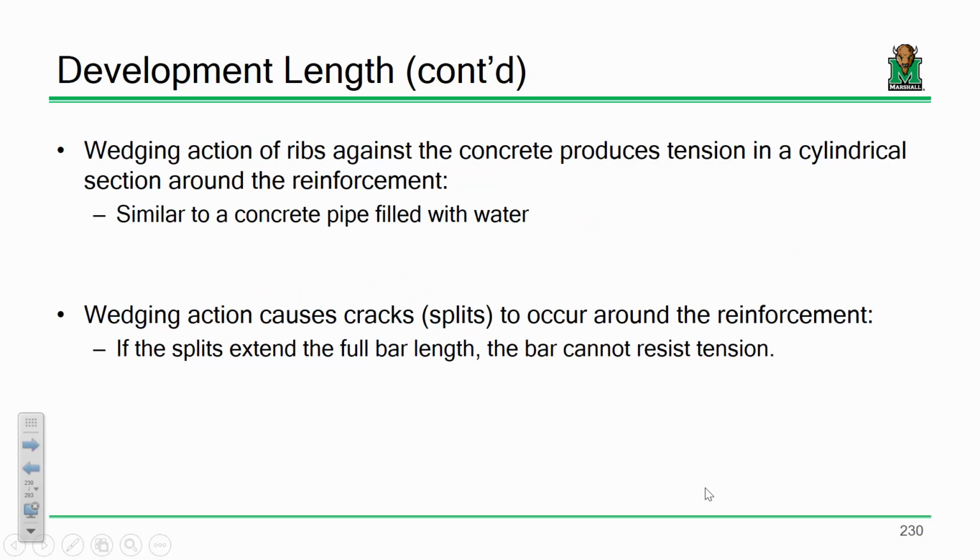Now, I want to show you something real quick. Let's go back to the analogy of the wall and the concrete. What happens with bond failure? Imagine I have that bar embedded into that wall. What happens if I actually start yanking on it? So let's say I have a bar right here. This is a bar of steel, or a rebar, and it's sticking out of the wall and I'm yanking on it. Okay, and let's say here's the beam in consideration, and it goes on like this.